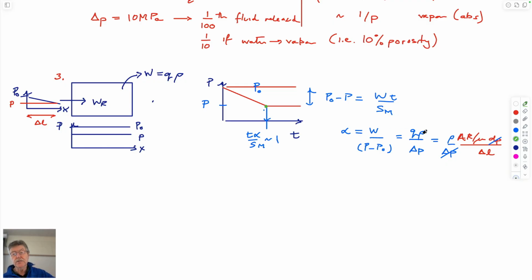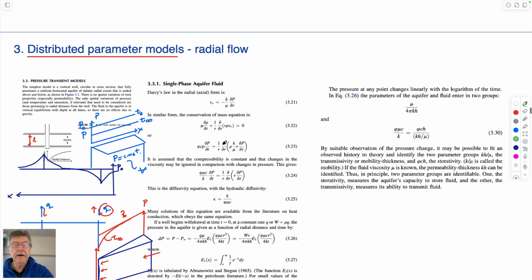If we define that in terms of a flow rate, we can substitute this for Darcy's law, written in terms of pressures. And if you substitute that in, that gives us this coefficient, links it to reservoir properties and rough areas of flow that we could imagine getting, and lengths of the boxes to be able to actually turn it into something useful. So that's where we left it last time.